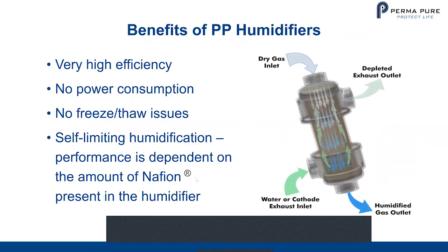So in the application, the benefits of Perma Pure humidifiers are, first of all, they are very highly efficient. There's no power consumption, no freeze-thaw issues, and there's a self-limiting humidification. The performance is strictly dependent on the amount of Nafion present in the humidifier.